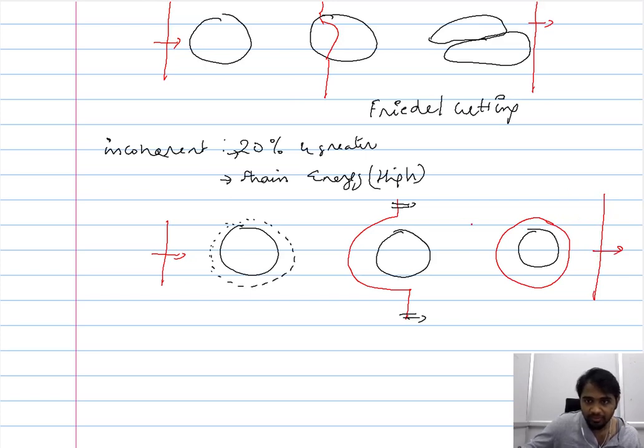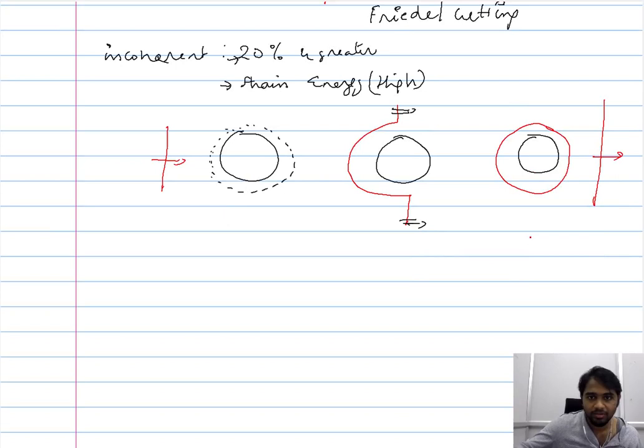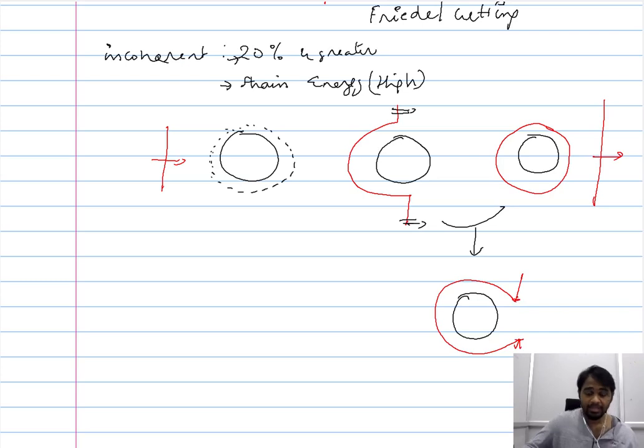The intermediate state between moving around the section of the dislocation will be of this form. So between these two, you have a state wherein the dislocation line will have a shape of something like this, and since these two sections are propagating in different directions, and the magnitude is the same, they annihilate with each other and thereby ultimately leave behind a loop surrounding the precipitate.